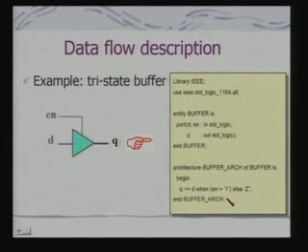Okay. So, if you look at when, why is it a data flow model? Because it tells you that when enable, if you consider when in a literal sense, it is associated with the concept of time. When this signal becomes 1, then only that Q, okay, should be representing D, otherwise it would be set to Z. So, it is a data flow model, it is not just a behavioral model.